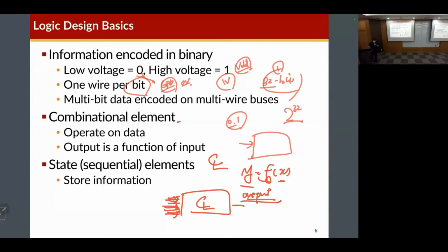In the real world, we need to consider the delay. So that means the time. So output is generated from the combinational logic, but after some delay, delta t. So this is the real device, real CMOS logic. And the CMOS logic has delays because the CMOS logic has a resistance part and also a capacitance part, and then resistance and capacitance determine the delay of this CMOS logic.